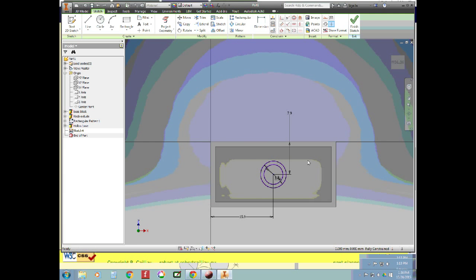That gets me out of the dimension. And now I can extrude that, but again I have to finish my sketch. Let's see. I suppose I could slide these in a little bit. They're not really a problem where they are. When you put your dimensions on your model, you just want to put them in a place that's convenient. The dimensions on the model are not as important as they are in the annotated drawing. In order to get a drawing of this out, you have to create what's called an annotated drawing, and then you tell it exactly where you want to put the dimensions, and there are specific conventions for that. We'll talk about that later.